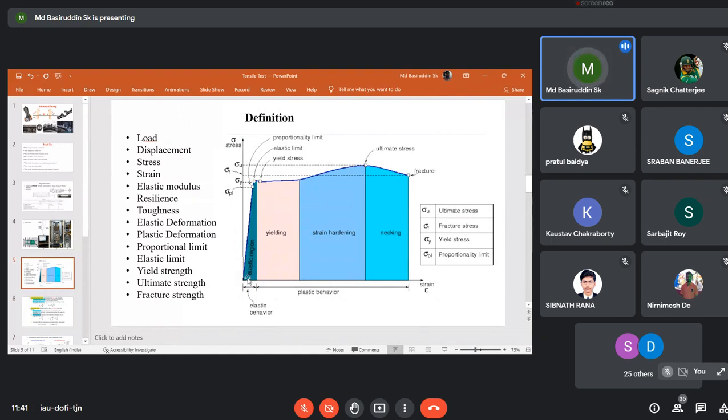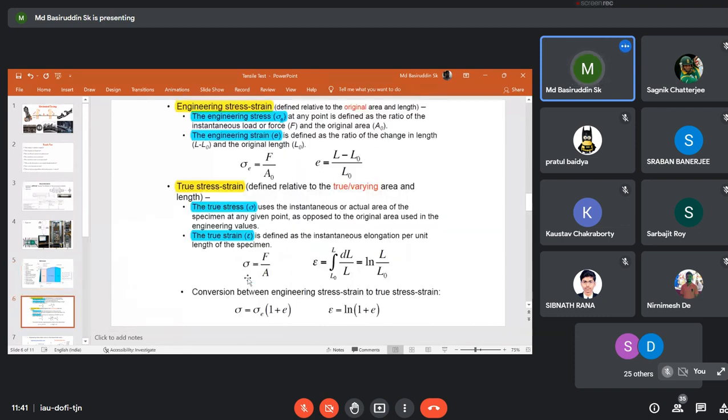Similarly, you can follow the same formula to evaluate the strain also, and then you can represent the true stress versus true strain data, the true stress true strain curve. Now, when you separate the engineering stress strain from the true stress strain, you need to follow certain symbols. For engineering stress and strain you generally find the representations like S and e.